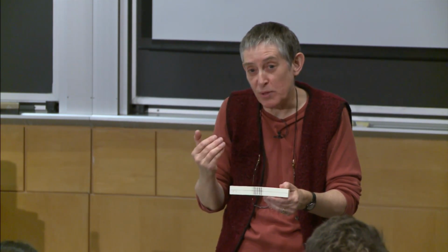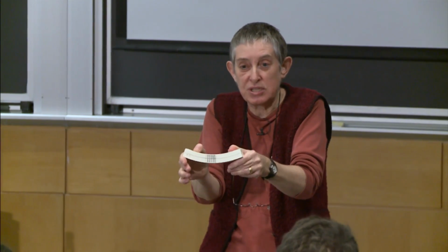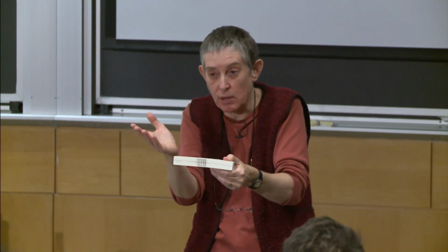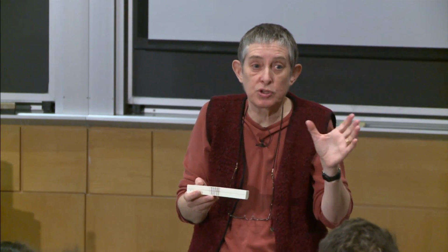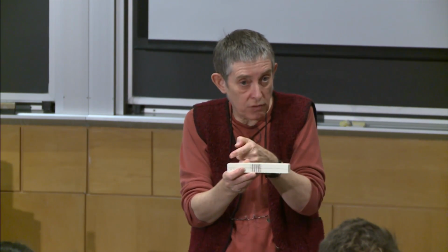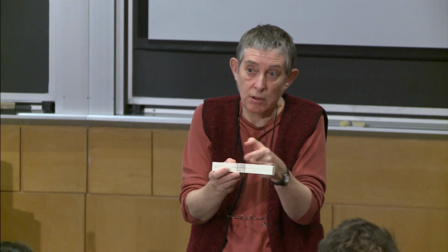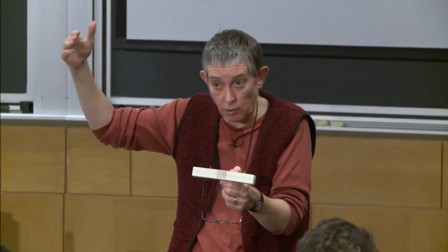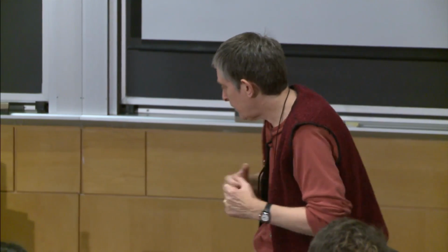So the bending moments relate to the normal stresses. So when I say that there's compression or there's tension along the length of the beam, that's going to be related to the bending moment. So the first step is we need to figure out what the shear forces are along the length of the beam and what the bending moments are along the length of the beam. Okay? And then next time, hopefully, we're going to relate that to the stresses. All right? So I'll pass it around so you can get to play with it and just mush it around a little.